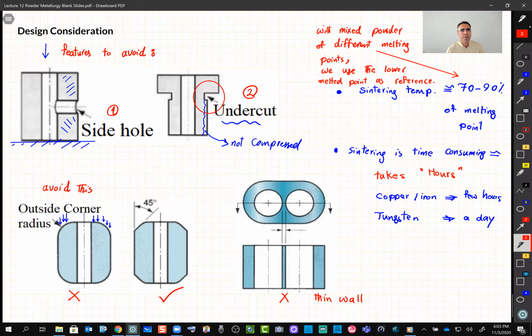it doesn't make a huge difference, because as long as we get to, let's say, 400 C in your example, and it creates the binding for that other one, we don't care about the other material with higher temperature getting too close to the melting point. You see what I mean? It's the lower temperature one that acts as the binder. We just care about getting that one to the melting point. So in terms of time, it may not make a huge difference.